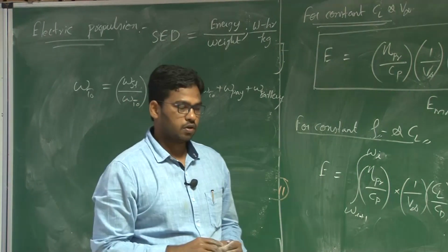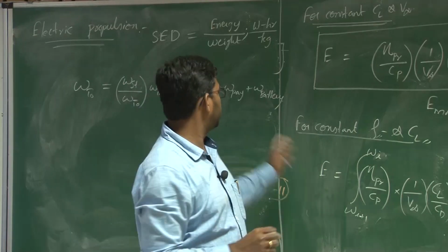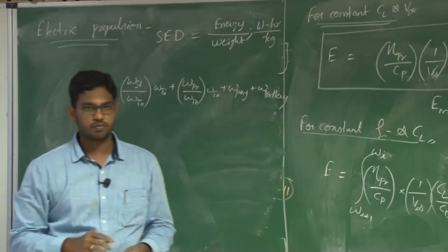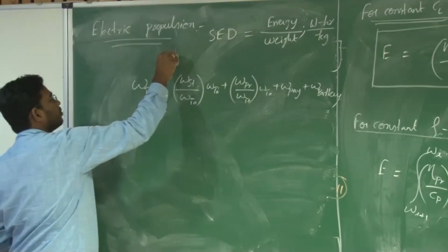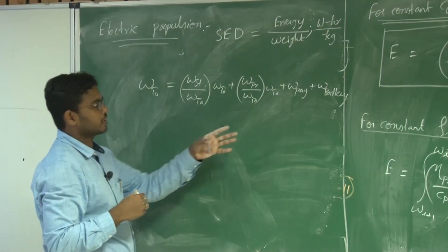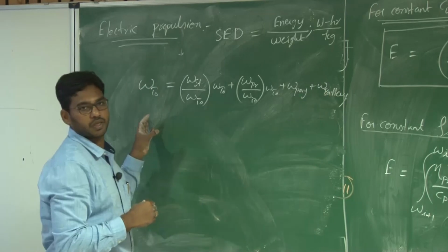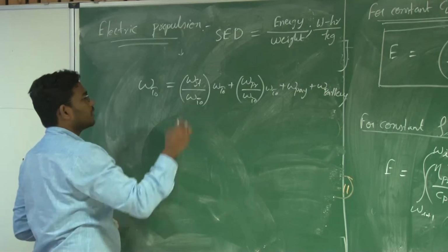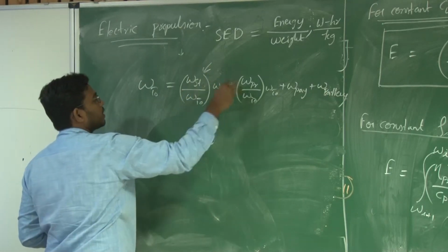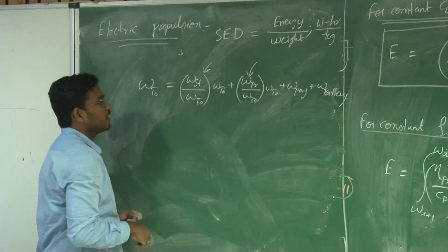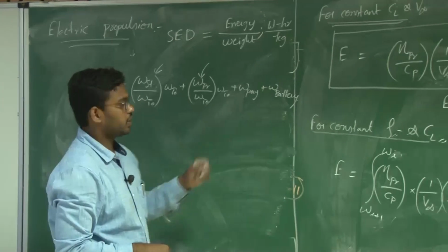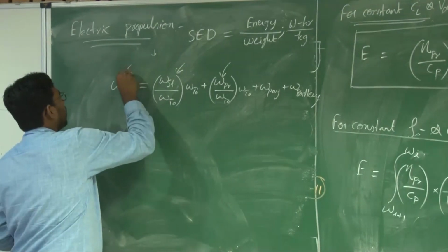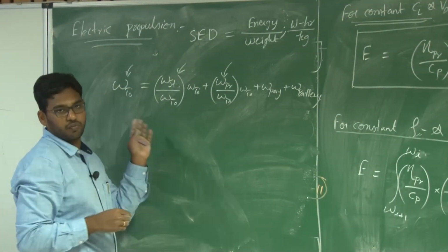Right. So it's a bit different compared to that of a fuel-based system. So what we go ahead with is, for this particular mission required, how do we estimate the battery weight and the overall takeoff weight? Similar to the earlier case, we consider the structural weight ratio and the propulsion weight ratio from the historical database, right? And we also consider the overall takeoff weight here.